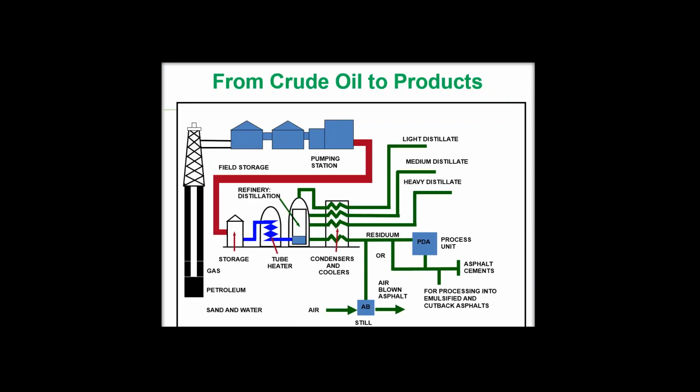Asphalt comes from crude oil. So the life cycle from extraction to the gate of the refinery starts with the oil well, bringing it forward to the refinery, with various processes in the refinery, which then result in breaking that petroleum source into various products, from gas at the upper light end, to asphalt, which is the heavier molecules in the barrel of oil, which are used to produce asphalt cements.